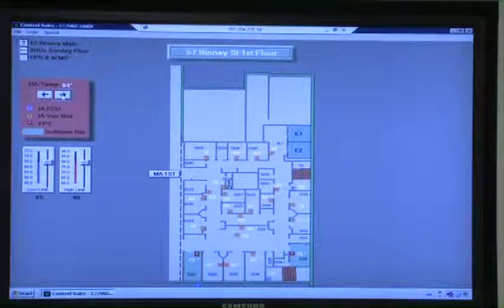Anybody else want to do anything on this floor here? So, you see the blue T-stats: fan coils, fan power boxes, just regular boxes, isolation rooms. We talked about the isolation room graphics. We talked about all that, okay? All the isolation rooms, every single room that has pressure relationship requirements, which is different now, guys, you gotta remember, has a door contact closure.